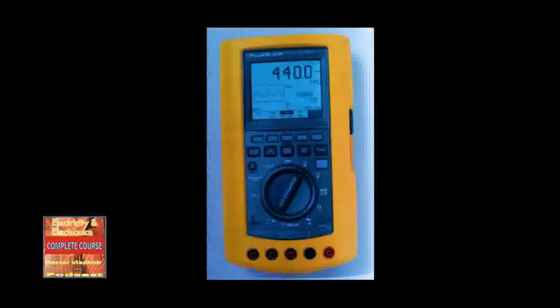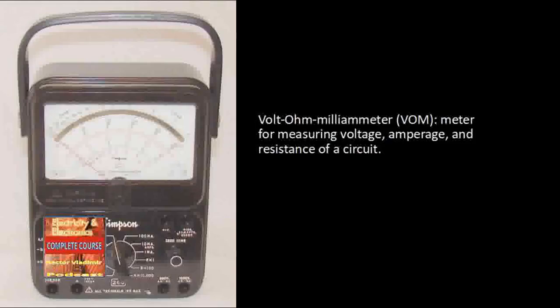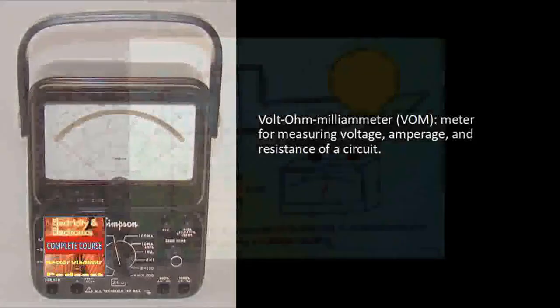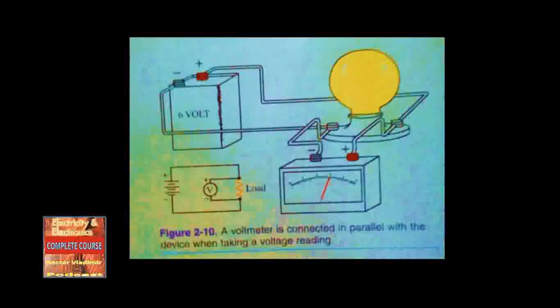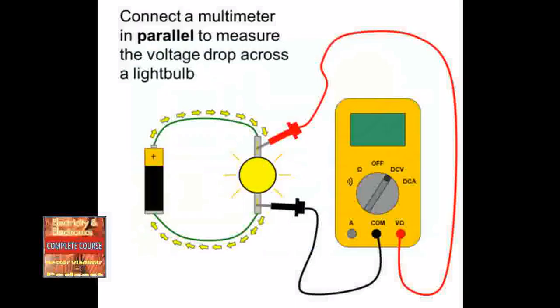Important meter information. Multimeters are very useful tools. There are a number of important details to remember when using these meters. A meter is a delicate instrument. Handle it with care and respect. Jarring, dropping, and other rough treatment can damage a meter, especially coil meter movements. When measuring voltage, the meter must be connected in parallel to the device being read. Start on the highest range when measuring an unknown voltage and move slowly to a lower range for increased accuracy as needed.